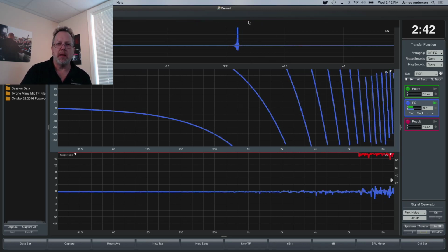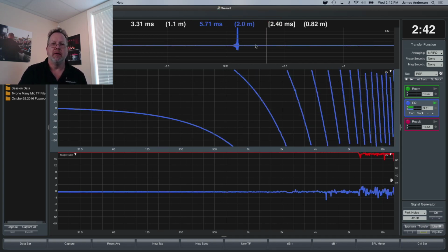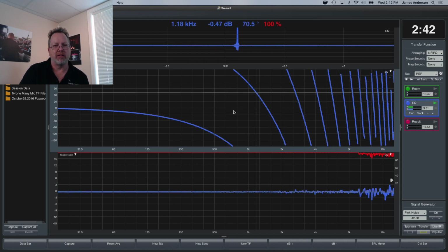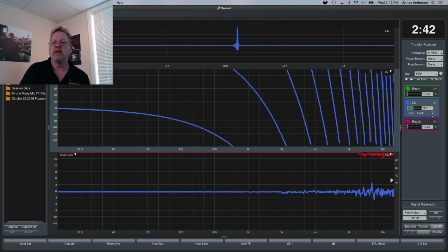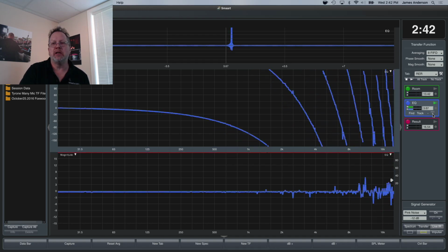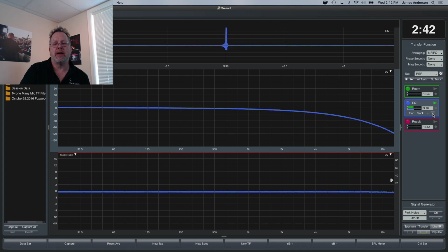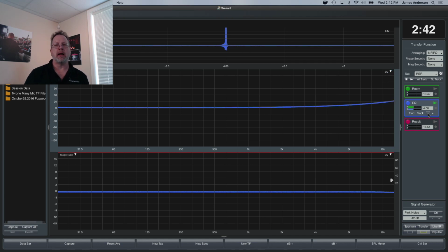This is the time domain view of the response of the system. This is the frequency domain view of the system. This is saying that he is lagging by something less than a millisecond. So is this. They're both saying the same thing. And so I'll come in here and as I bring them into time with each other, you can see the phase trace flattening out. Oops, I went too far. I'll go ahead and knock it back, brought it back into time.